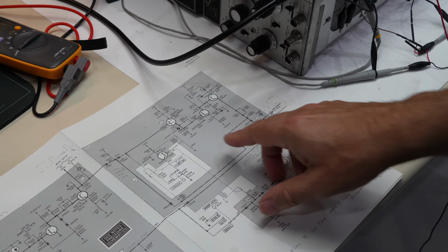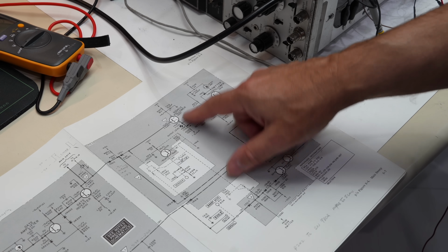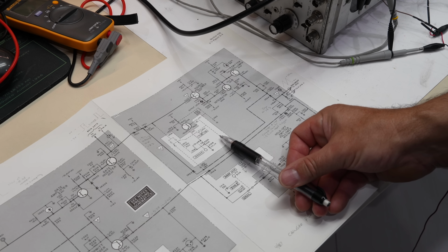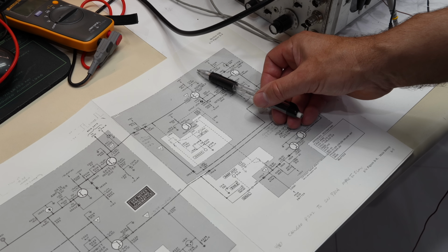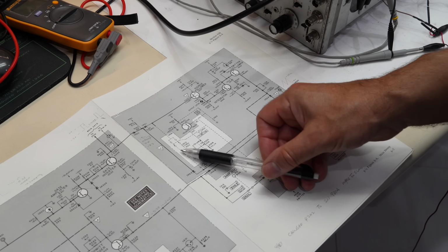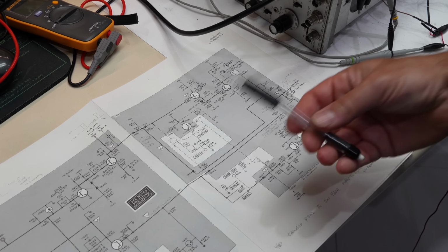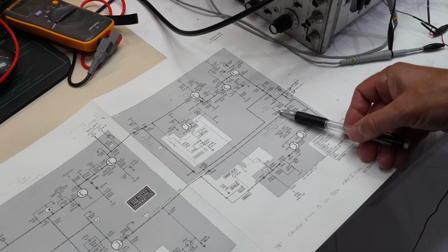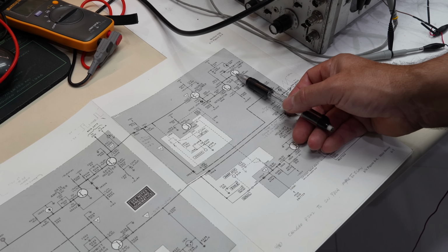And my hunch is that the sweep circuitry is working too, because in some cases when I was tweaking the button I got one sweep. So I already have an inkling of what's happening. I think this works because I saw the dot moving across from time to time. It goes up and then the dot is stuck somewhere, I think towards the right of the screen, and somehow this cannot detect the end of the sweep and never resets. That would be my working assumption.